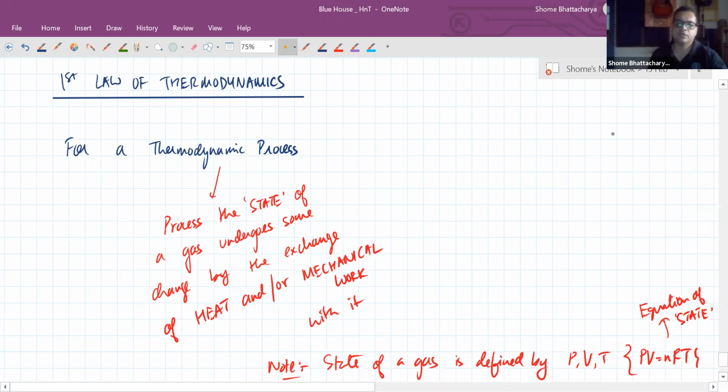When their temperatures are same. Whereas when do they exchange heat? When they are at different temperatures. So that's all about zeroth law. You don't need to really know anything separately about zeroth law. It's more about the law of calorimetry. That is, in any heat exchange, the heat lost by the body which is cooling down will be equal to the heat absorbed by the body or material which is heating up till they achieve equilibrium. That is, their temperature becomes common.